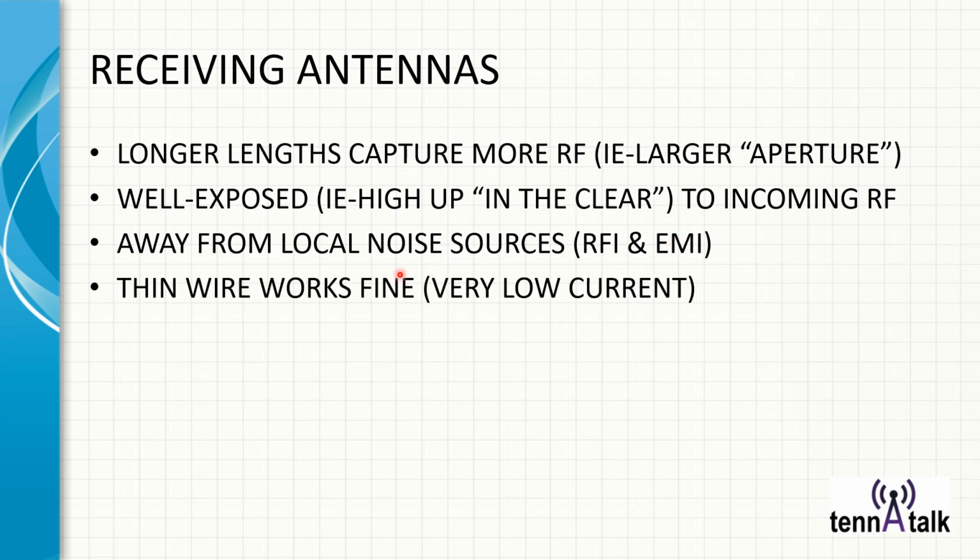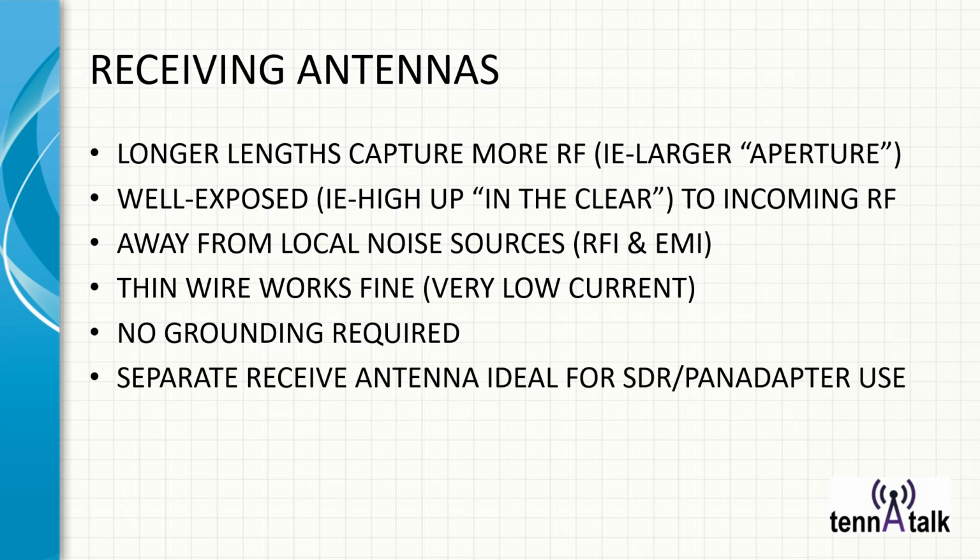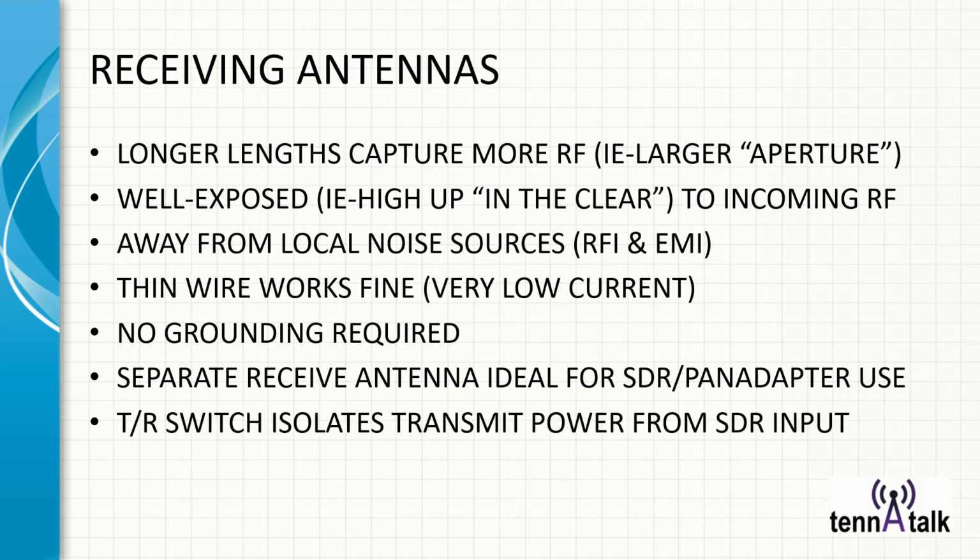Thin wires work fine for very low current. No grounding is required, and a separate receive antenna can be very helpful, especially if you're using it with an SDR pan adapter. If you do that, you want a TR switch to isolate your transmit power from your SDR input.